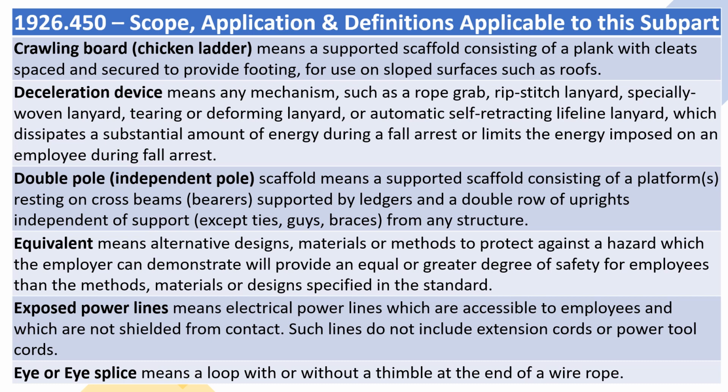Equivalent means alternative designs, materials or methods to protect against a hazard which the employer can demonstrate will provide an equal or greater degree of safety for employees than the methods, materials or designs specified in the standard. Exposed power lines means electrical power lines which are accessible to employees and which are not shielded from contact. Such lines do not include extension cords or power tool cords. Eye splice means a loop with or without a thimble at the end of a wire rope.